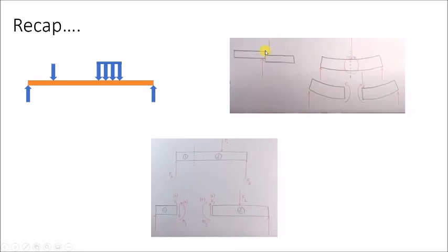So we've got this downward force here and an upward force here, and if the beam was to fail due to shear force, it would literally be cut off at that point, where the shear force inside couldn't resist the external forces, the upward and downward forces being put upon it. If the internal shear forces couldn't equal the external forces, then the beam would fail and cut off at that point.